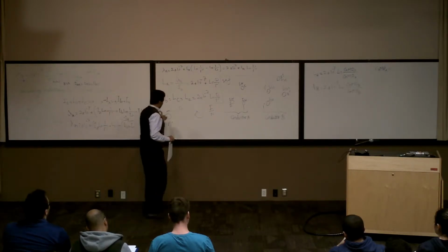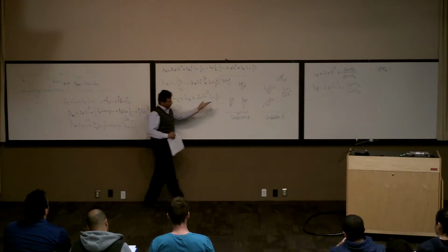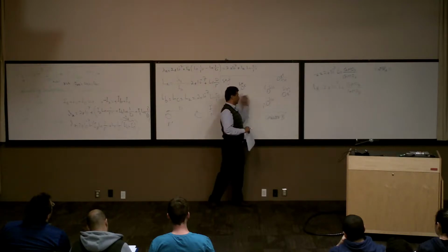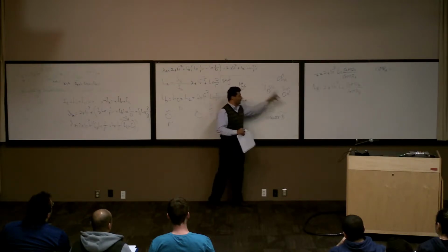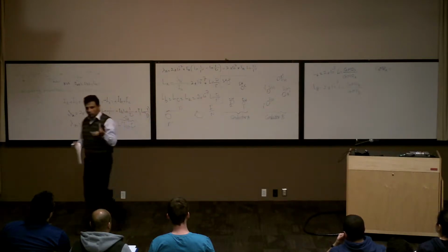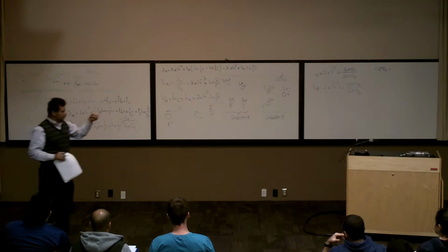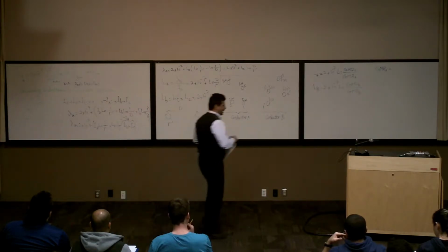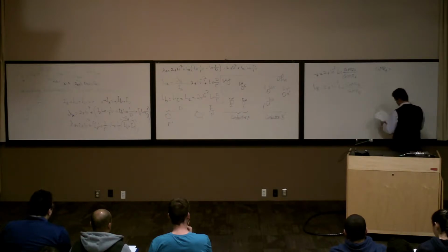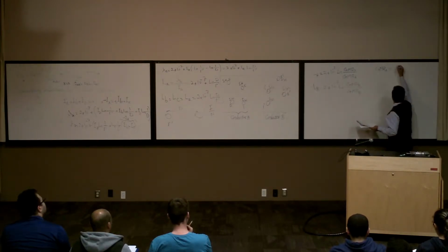Again here, for example, it's simple. From this conductor to this conductor is B. Now which one are you going to consider? We have 4, it could be this one to this one, or that one to this one. We have many of these instances. We need to come up with a kind of average of those instances to see how much it is. So GMR and GMD will give us those kinds of averages. GMR, for the conductor A, is equal to